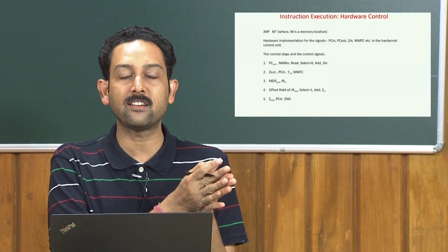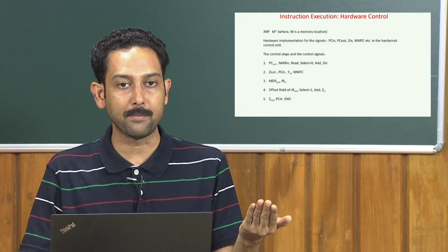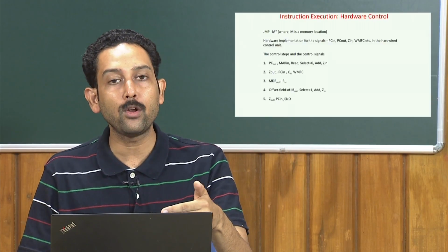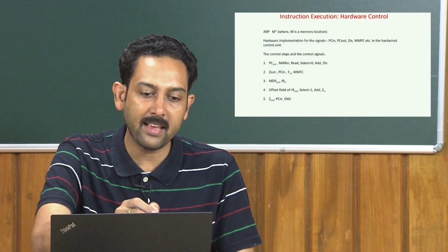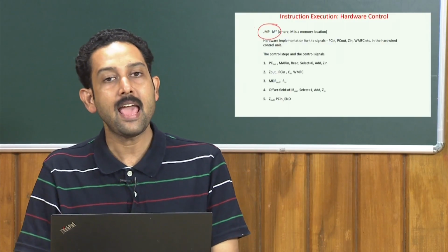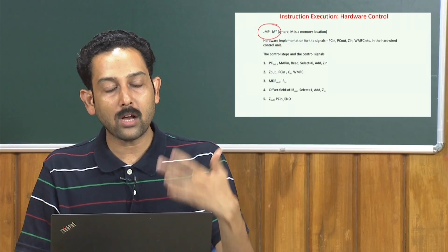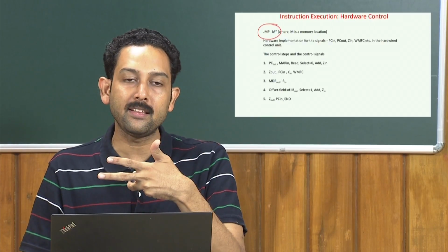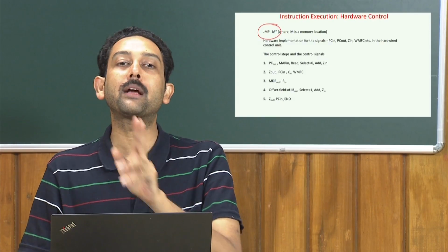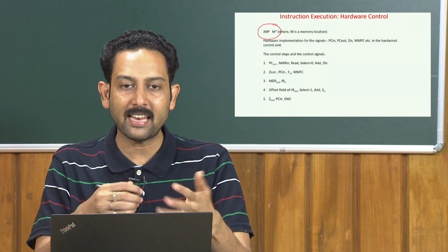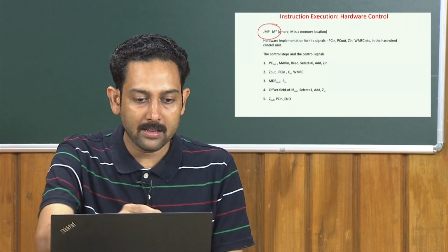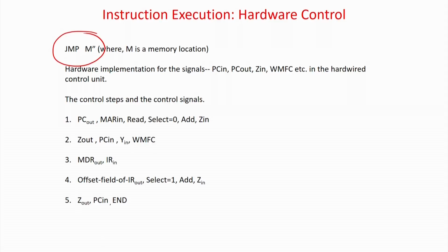Till now the last instruction was a simple non-control based implementation, just a flow. But here we are going to see two types of instruction: one is an unconditional branch and the other is a conditional jump. For the conditional jump, the corresponding instruction will have another input which will come from the flag register, so that you can get a basic idea.